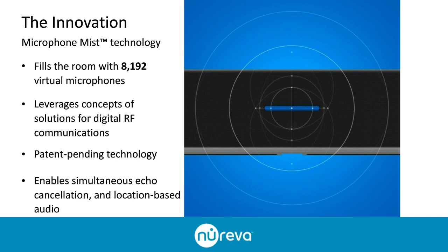So I think the key is the words that I used was XY location in an actual space. Beamforming utilizes a vector-based approach to say, in this direction at this angle, I'm hearing someone speak. So classic beamforming is taking quite a bit different approach. And then as a second person starts speaking, it needs to switch from that particular vector to a new vector. And it's not telling you where along that vector that particular person is speaking. So it's a different approach.